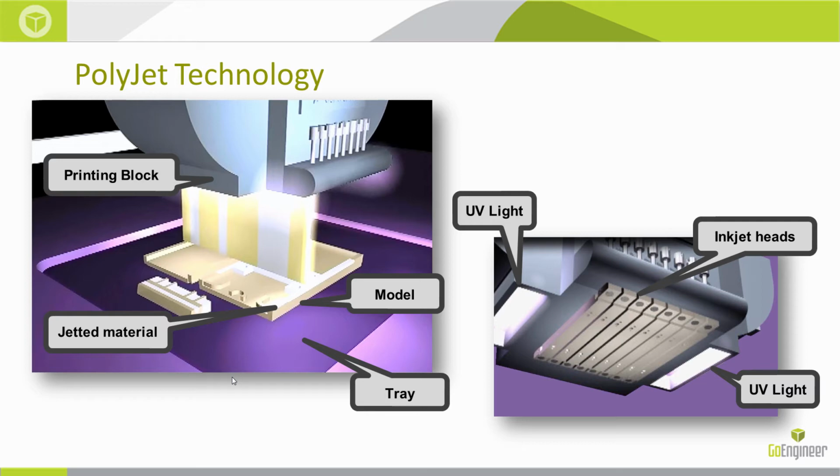So on the PolyJet side, the analogy goes pretty far. We have a machine with a print head, or maybe 2, or maybe 3 print heads. We have some ink cartridges or material cartridges. We load up a basic number of cartridges, and the printer software can mix those cartridges, mix those inks together to create new materials. One piece of hardware that's different is that we have a UV floodlight. And that UV floodlight cures the photopolymers, cures the material after it's been dropped down.